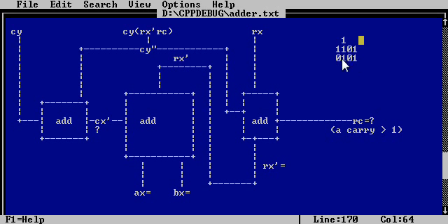And I want this to work out in the way addition normally works. If all 3 of them are 1s, in that case I want to have a 1 here and carry over. If two of them are 1s, I just want to get a carry and a 0, and so on and so forth.